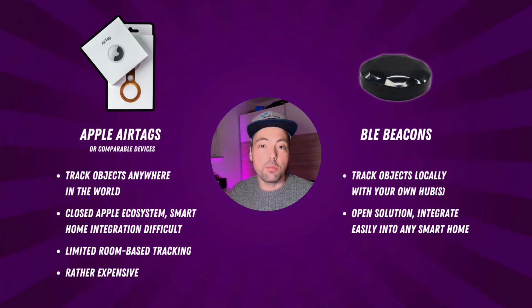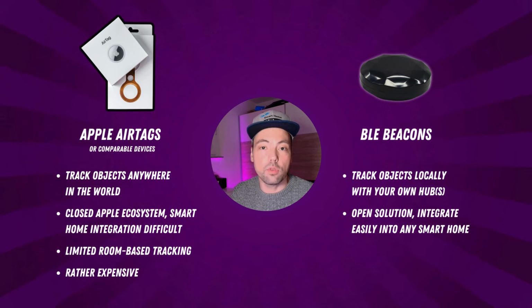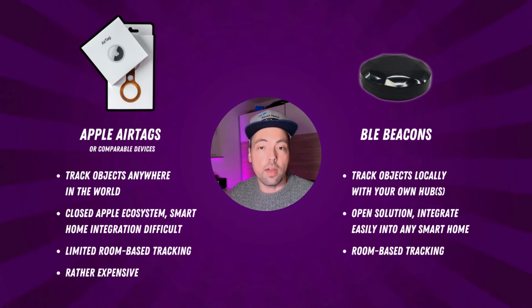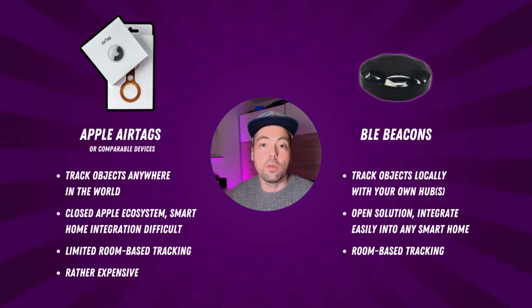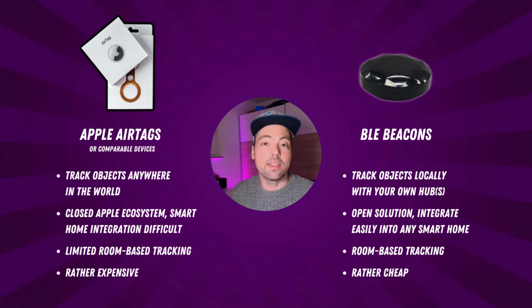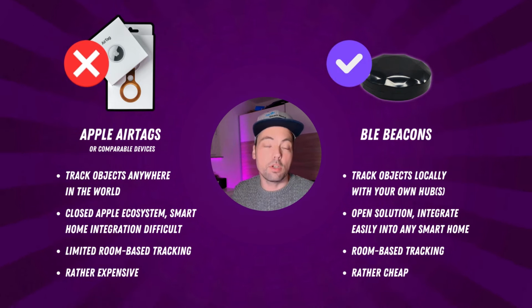So this is more of an open solution, because there are many open source solutions out there which allow you to build up such hubs, and then you can also easily integrate with your own smart home solutions, whatever it is, Home Assistant, IO Broker, or whatever you have. Because usually those open source hubs also integrate with standard technologies, such as MQTT, in order to be able to send the tracking information to your smart home. And this is really cool. Also a benefit of those BLE beacons is that they are usually rather cheap and you can buy lots of them in bigger packages. And so that's why I have decided to go with the BLE beacon approach for this project.